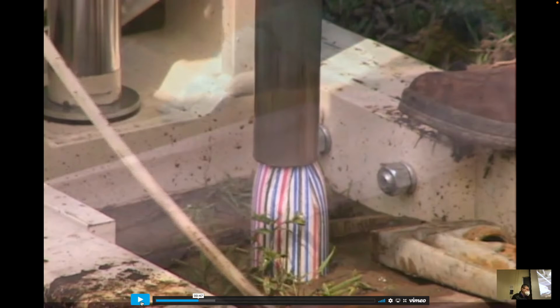It gets pushed down to the bottom of the hole, and then once you're at the bottom of the hole, you have the sacrificial tip on the probe, which gets left there like a barb on an arrow. Then you pull the rest of the tube up through the hole, and you leave a string that has a central piezometer, a tube maybe an inch in diameter that can measure the pressure and sample fluids from that depth.